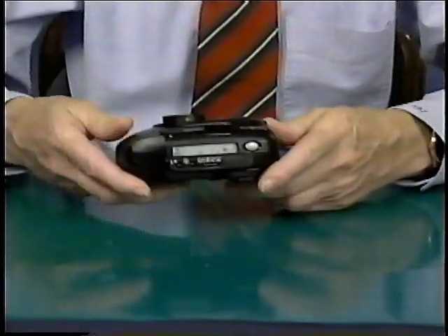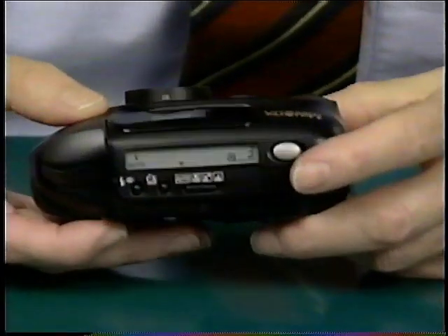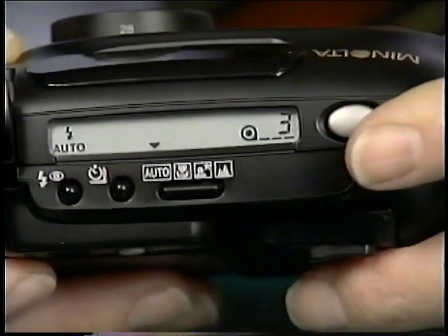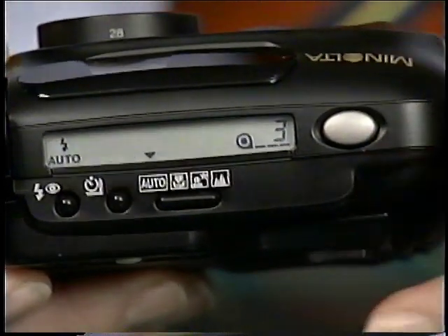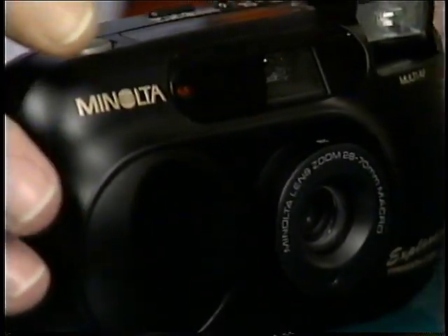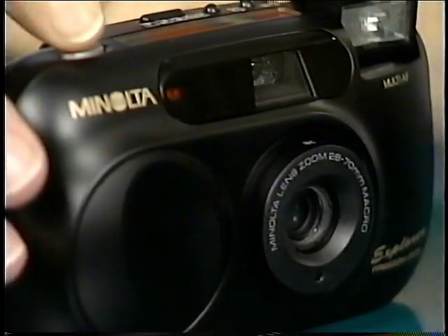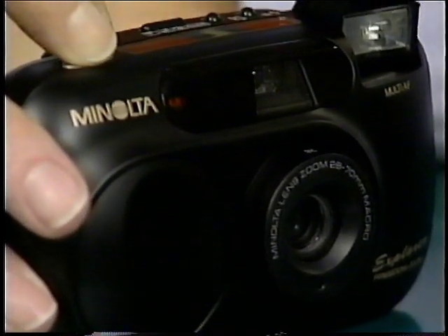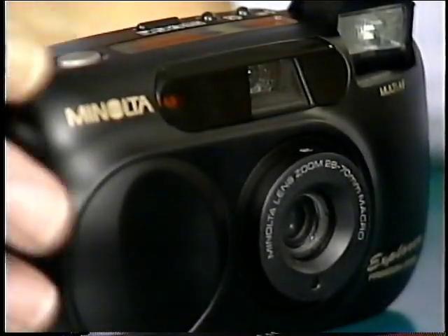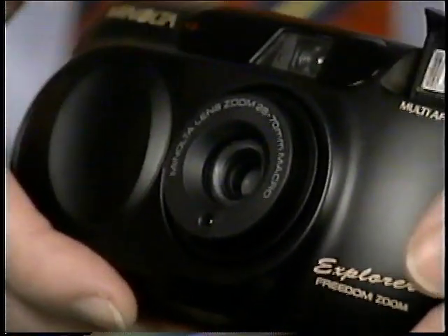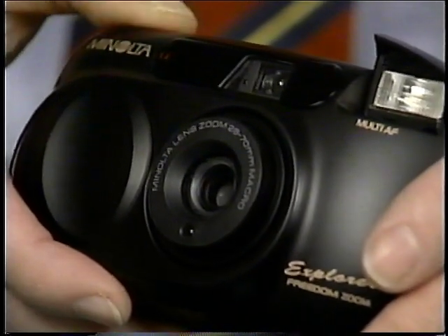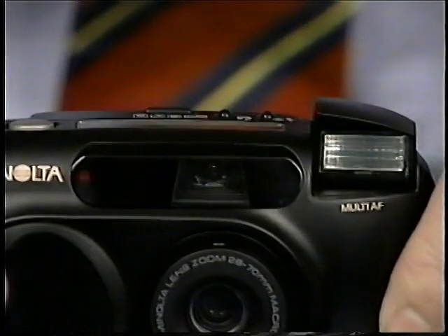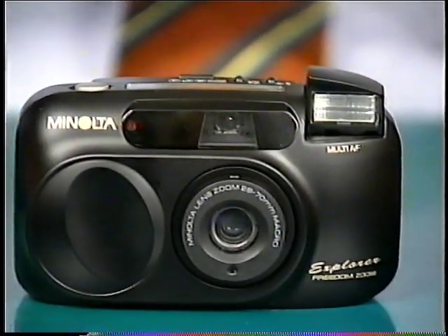Testing exposure on lens shutter cameras is quite simple because they have auto flash or automatic flash for dark situations. And if the mode is selected, and it is here, in other words, we've selected auto flash, it should do just that. In other words, if we darken or point the camera toward a dark area, you can also cover the light detector on the front of the camera. But if we point the camera toward a dark area, it should flash during an exposure. If we point the camera toward the lights, it should make an exposure without flash. If it's doing that, the metering system is working on the camera.